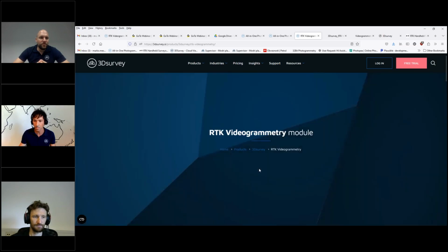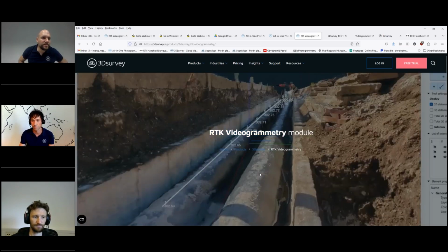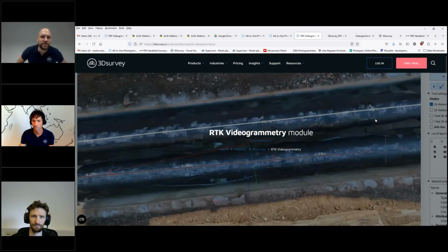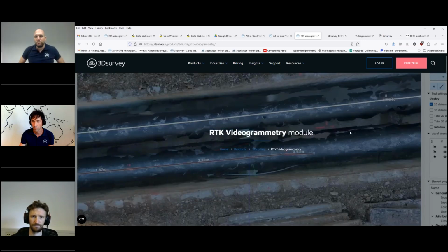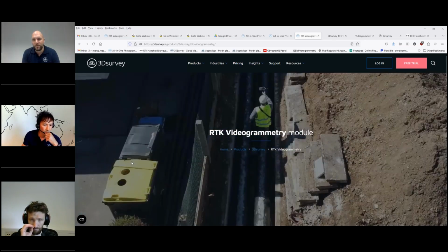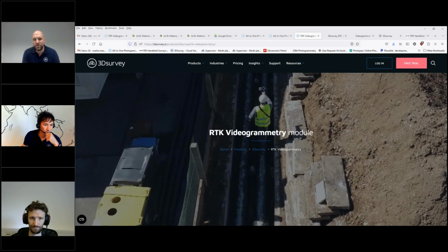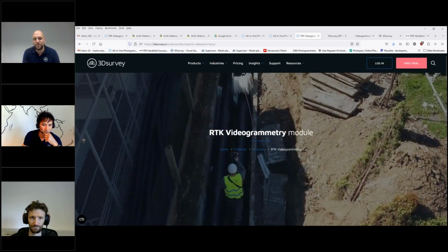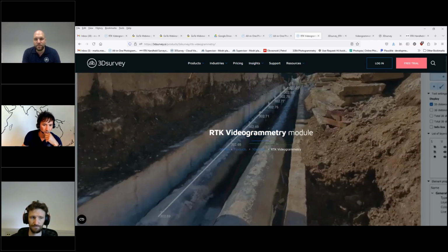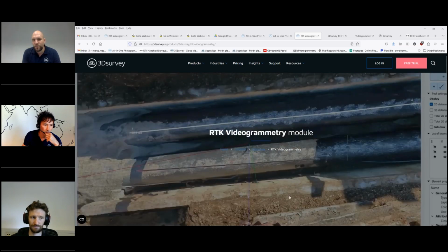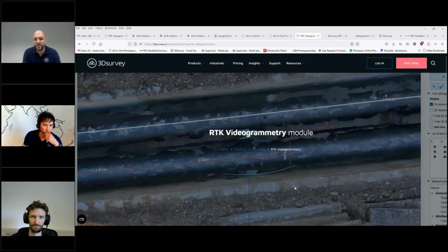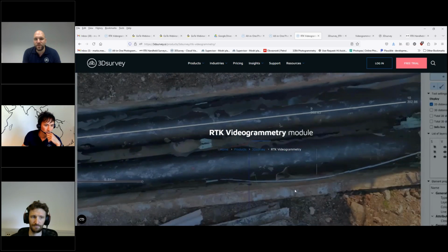Okay, Vit? Okay, then there's a question from Michelle. He's asking, do you have a function to semi-auto-detect quarry crests and foots? So actually with the next update, coming probably sometime around IntelliGeo, we will have a new function that automatically detects break lines. But secondly, even today, you can create vertical cross sections or profiles, and then you can add points to those profiles.